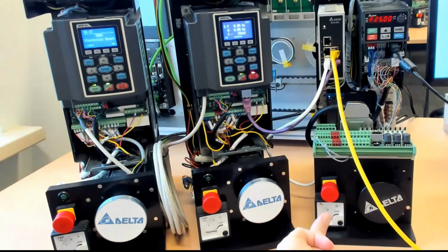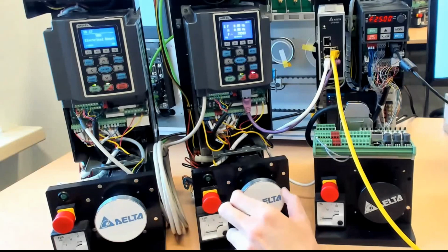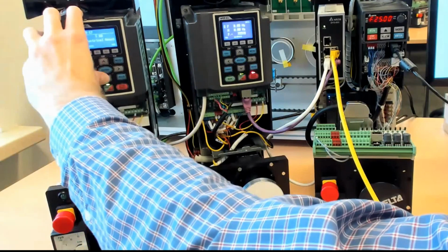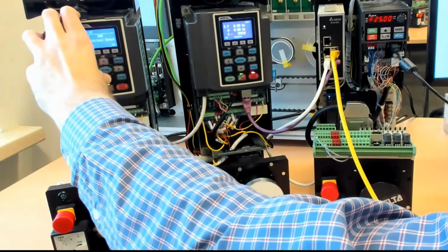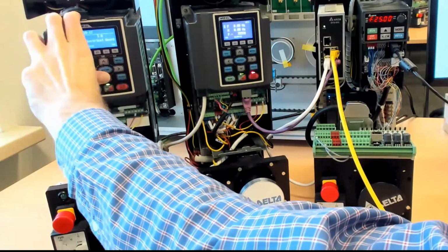There are, of course, more drives, more settings that you can play with. So, for instance, also the current gains. It's important to be able to configure so that you can actually determine how strongly the drive reacts to a change in load. Okay, so you can also set a smaller ratio between the master and follower drive.